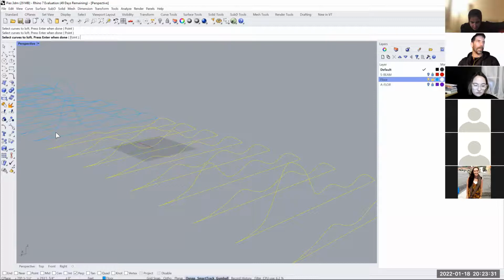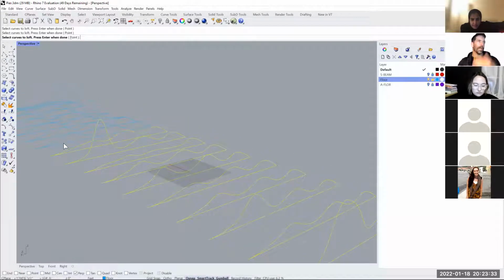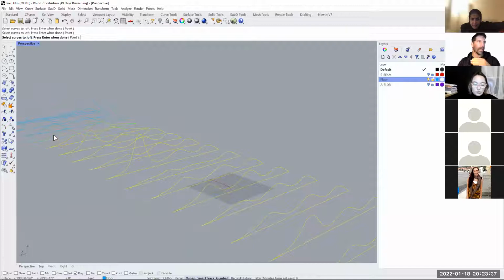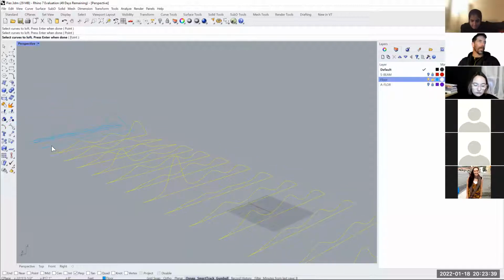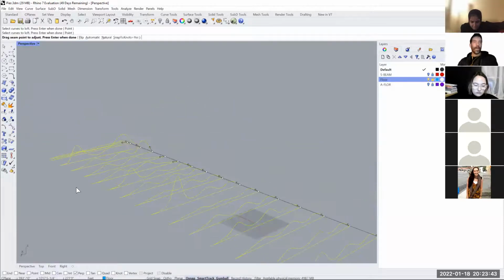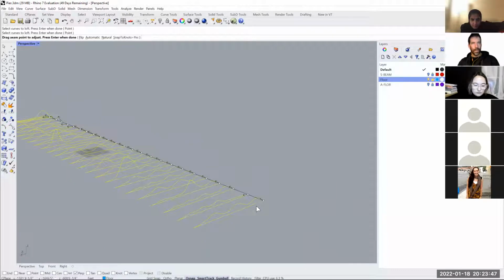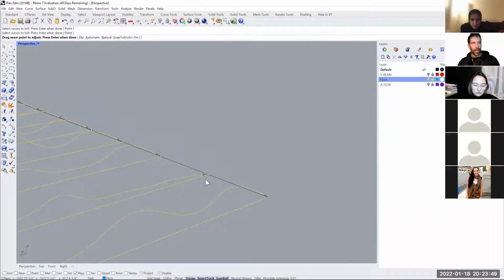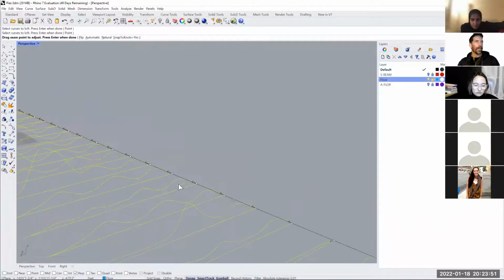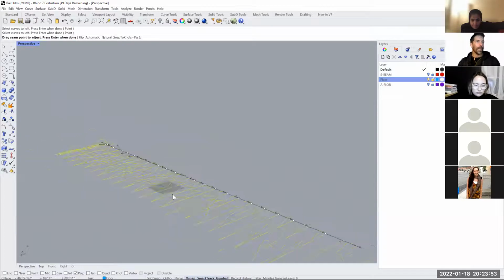Try to be consistent in where you click, and the order of how you click has to correspond with how you want the surface to join. Ideally the curves have this point in the same place, and the arrow goes and looks in the same direction. Because it's the same curve copied and then modified, this tends to work quite well.